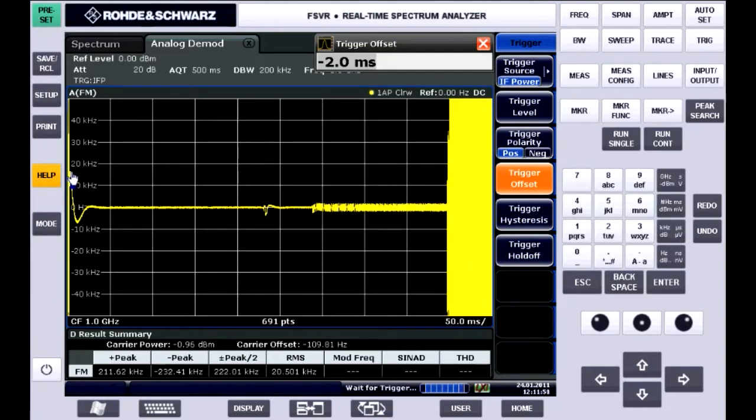So there's settling. When the power turns on, the frequency is roughly 16 kilohertz low, and then it goes to about 6 kilohertz low, and then finally settles out. I also have a small frequency glitch here. Don't know what that is, but it's in the signal. And then we finally get to these tones, which the walkie-talkie produces as signaling tones. That's just simple audio right there. And this tells me a little bit more about the signal, but it doesn't tell me everything.